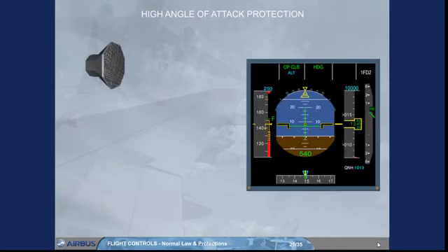A low energy sound, "speed, speed, speed", repeated every 5 seconds, warns the pilot that the aircraft's energy level is going below a threshold. Under this threshold, the pilot must increase the thrust to recover a positive flight path angle through pitch control. The FAC computes an energy level, taking into account the configuration, the horizontal deceleration rate, and the flight path angle.